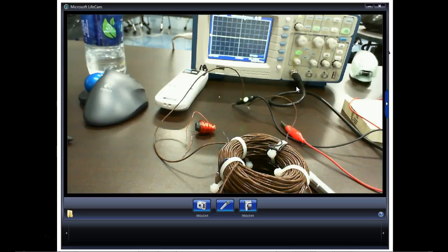If I put 100 volts over here, I get 50 volts over there. But vice versa, if I had 2 turns on my secondary for every 1 turn on my primary, then if I put 100 volts over here, I get 200 volts over there. So with transformers, we have what we call step-up transformers, and we have step-down transformers.